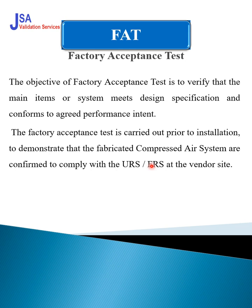If you identify any gap from the user requirement specification or design specification, or there is any additional requirement, then you go for the MOM, or you raise the requirements, and they will implement it before shipment of the equipment. The objective of the factory acceptance test is to verify that the main items of the system meet the design specification and confirm the agreed performance intent. It is carried out prior to installation, before shipment to the customer side.